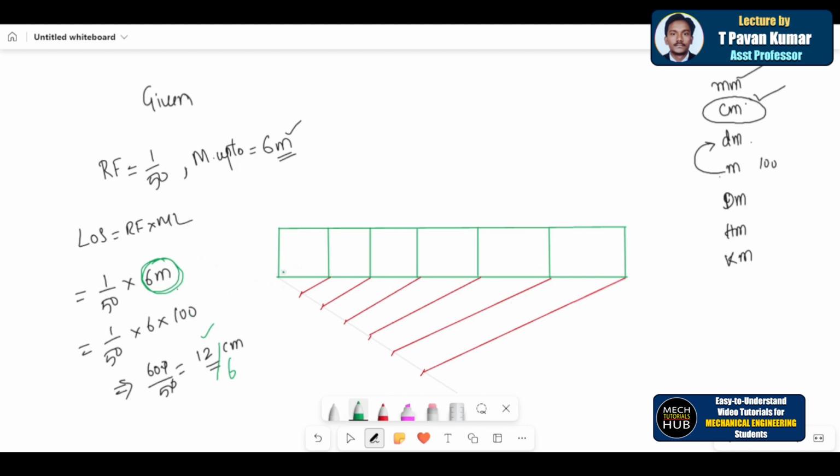Now this particular scale reads meters and decimeters. Okay, so how to place the division? This first division, 0th division, 1 2 3 4 5, 6 parts, 5 numbers I got it. Okay, now the first division I'll try to divide it, a central line at 5. This is 5, means 10. So this will read the subdivisions, decimeters, this will read the main divisions, meters.